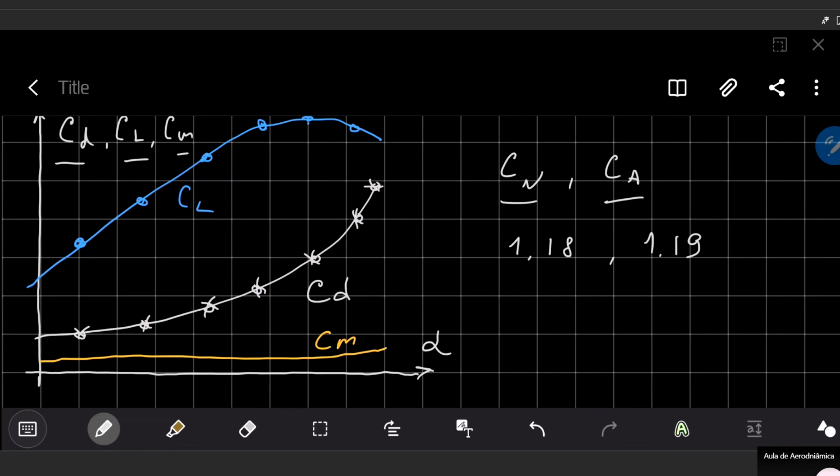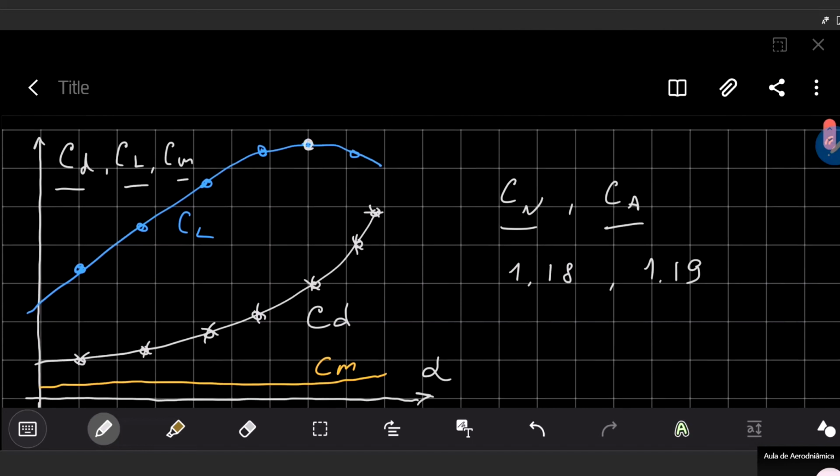This was the answer on your first question. No, you work with the constant slope of the lift coefficient. We are not working in aerodynamics with the angles higher than the maximum possible or so-called stall angle of attack. Okay, you do not need to explain what happens here in this region because we are not working with flow separation. Actually, the modeling of the flow separation is outside of the first part of aerodynamics, which we study now.